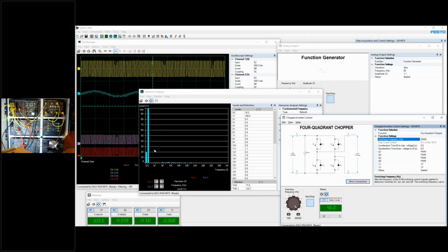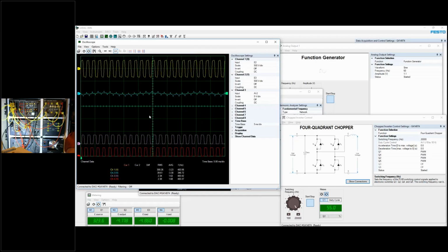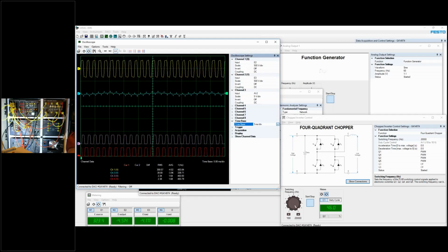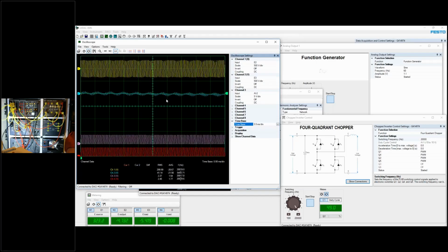And by the way, that's the reason we typically use really high switching frequencies for these power electronics devices, so that they don't annoy the human operator like this. And now, if I switch back my oscilloscope, the frequency is so high that the oscilloscope is not able to display the discrete peaks. I have to zoom in to be able to start seeing them again on this signal, as you can see. But anyway, any other question?